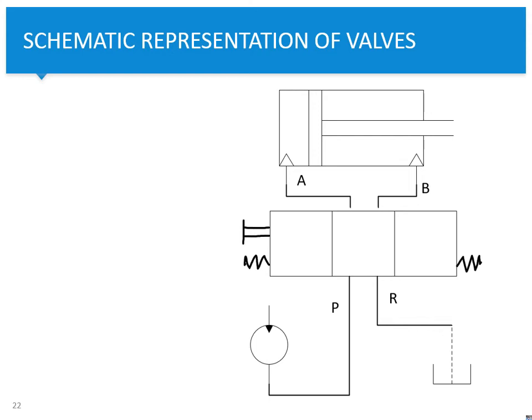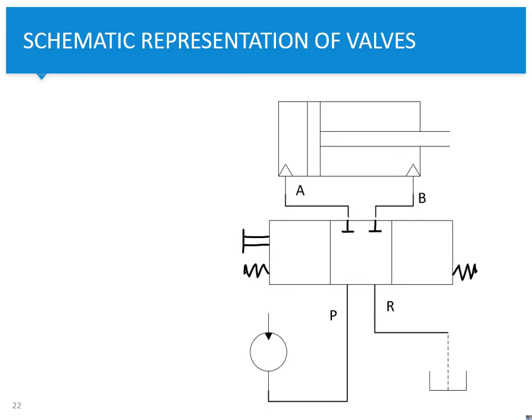4-3 valve. Okay, and now in the rest position, the cylinder will be blocked, so it will look like this. So no flow can go in or go out. And in hydraulics, you can represent it like this, since we know that oil can't be compressed, or only up to a very limited amount. So we know that this is sufficient to keep the bucket in position.